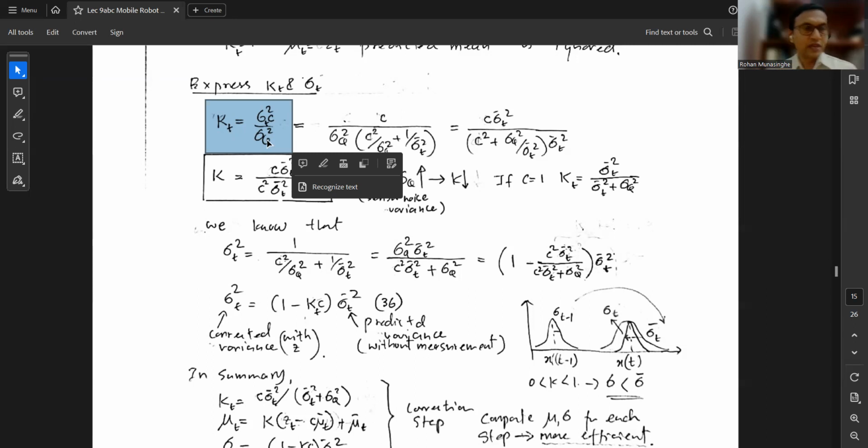For example, if you take the two-wheel mobile robot, when the wheels turn, the robot moves. So there's of course an error here, right? You cannot precisely say where the robot is by just looking at the wheel motion. If you turn the wheels 100 times and you expect it to be at some point, when you measure it, it's not there.